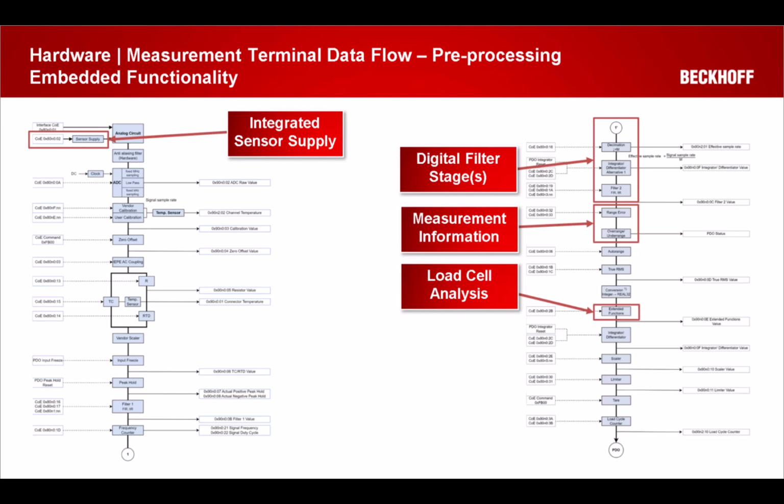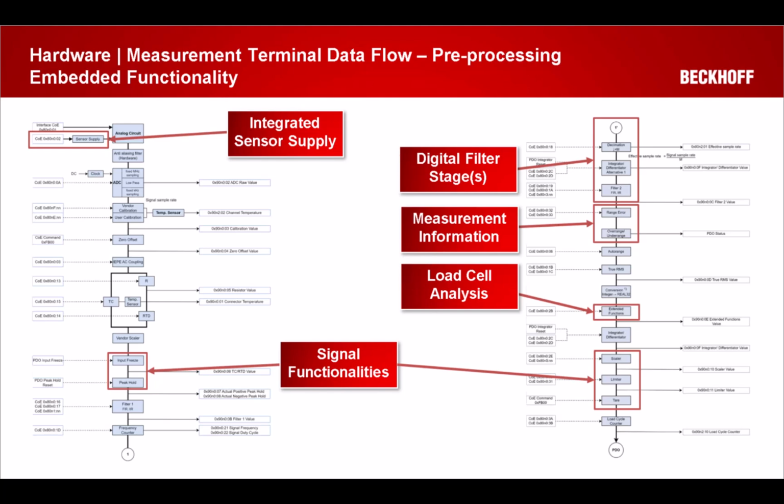So you can take a signal coming in and give some very basic specifications around compression and tension, parameters, gravity, and other values to essentially present a scaled load cell value that can be linkable and used in software, as well as other functionalities, which are pretty standard around input freeze, peak hold, scaling, limiting, tare functionality, and more. And at the very end, we have usable sensor data, which we'll unpack a little bit later.